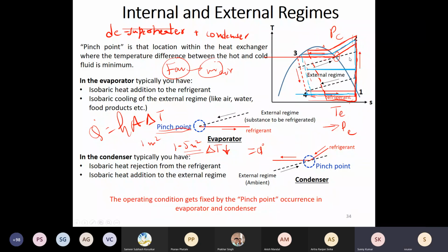So if you just take out the compressor from a 3-star AC and you connect it to larger heat exchangers, the same compressor would be consuming a lesser amount of work. We always think that the innovation of a 5-star AC vis-a-vis a 3-star AC is only the compressor. That is not the case. The extra money that you pay is spent both on the compressor as well as on the heat exchanger area.